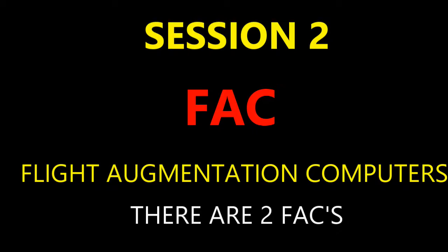Now you also have a manual mode. So when the autopilot's not engaged, okay, then you have the ELAC sending to the FAC. It's going to be sending for the Dutch roll damping, engine failure compensation, yaw orders, and also for the turn coordination. So those are the things that would be functioning, or be functions, in manual mode.